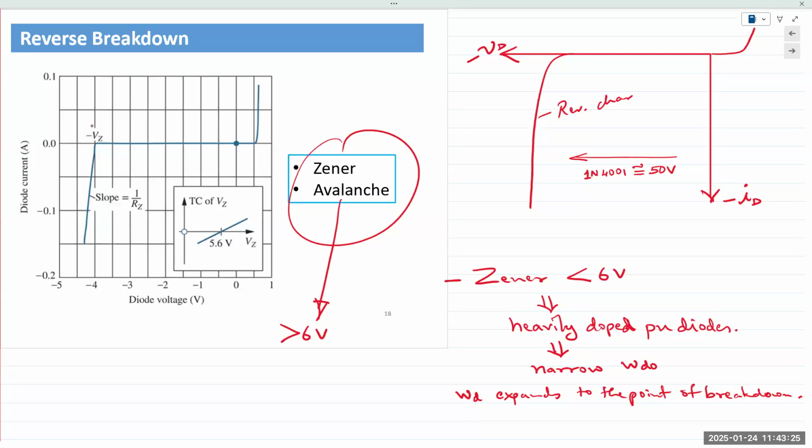The depletion region keeps expanding, and more and more ionized atoms are created on both sides of the PN junction. When it's a very high level of electric field, electrons are now breaking free of their bonds, and more charge carriers are being created. Every electron that breaks free of its bond creates an electron as well as a hole, so more and more are created.